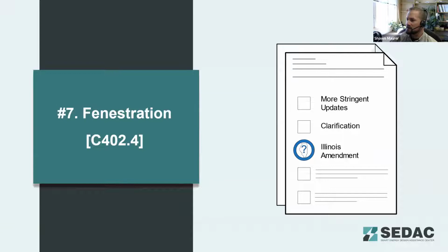Okay, let's go ahead and end our poll here and share those results. So for question number 1, looks like most people caught on. Yes, it was the non-swinging door insulation that had slightly relaxed requirements in the 2021 IECC. The others are either the same or slightly more stringent as the 2018. And then for tapered roof insulation, that minimum thickness is 1 inch everywhere. As far as the specific locations, that only refers to whether you can have a single layer of insulation or 2 layers, but you must have a minimum of 1 inch across the entire roof deck for above deck tapered insulation.